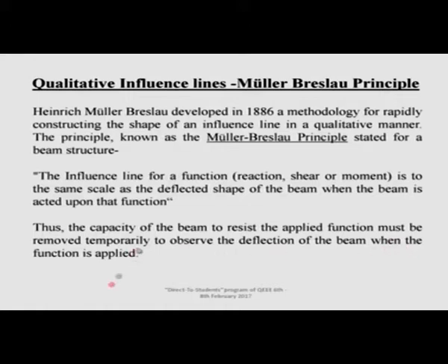You please go through once again. Let me display this page for a couple of minutes. What it says is, well, you want the influence line for the reactions, fine. First of all, deactivate the reactions. That means, suppose I am interested in the influence line diagram of the reaction at the left end. Let me destroy it temporarily.